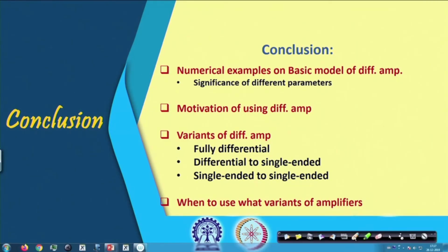So, first of all, we started with numerical examples on the basic model of a differential amplifier, and there what we have discussed is the significance or importance of different performance parameters, namely differential mode gain, common mode gain, then common mode to differential gain, and then differential to common mode gain.